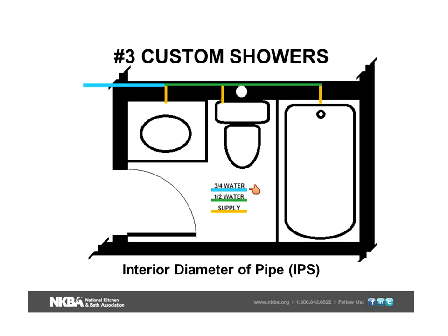You'll notice we have a 3/4 inch water line coming into the bathroom group from another area. Now, this is a traditional distribution system, not a manifold distribution system. And of course, I'm only showing one water line, but I think you'd understand we have a hot and a cold coming in. So we have 3/4 inch water lines coming in. As soon as we hit the first fixture, unless this requires a supply line greater than 1/2 inch, or the bathtub requires something greater than 1/2 inch, the plumber may change to 1/2 inch water line.